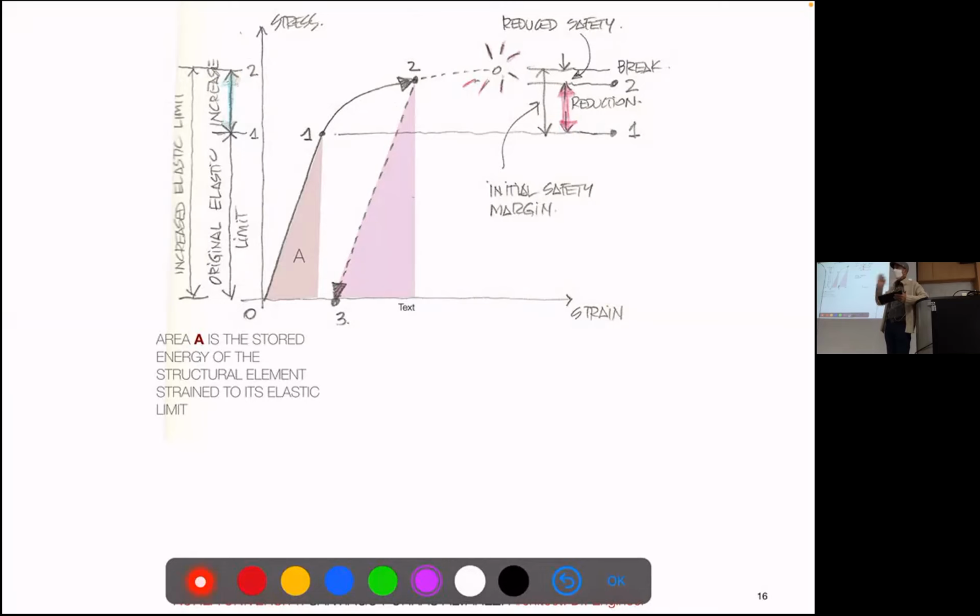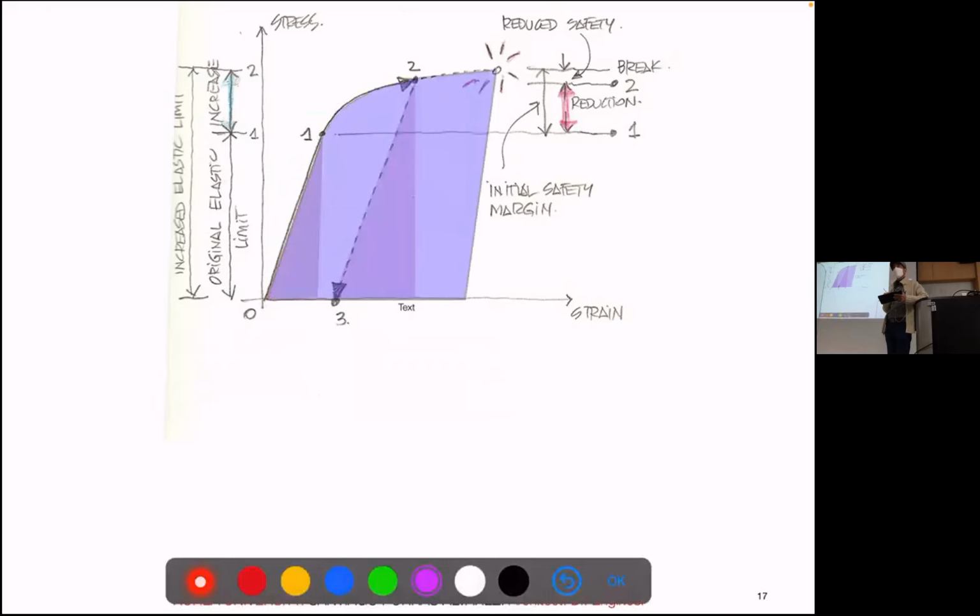But if we go from the beginning, so if we consider the elastic element, but it goes beyond the calculation to one safe plastic part, the energy that accumulates is enormous, right? It cannot be compared to that up to the breaking point. And this is what explains why, even though we have some cracks at some point, the structure can still absorb a huge amount of energy before it collapses. And this is very useful